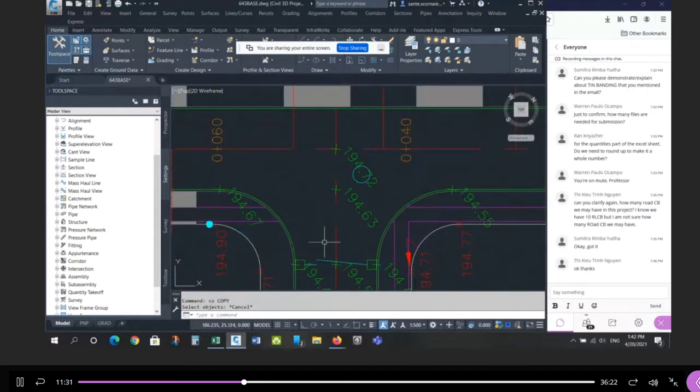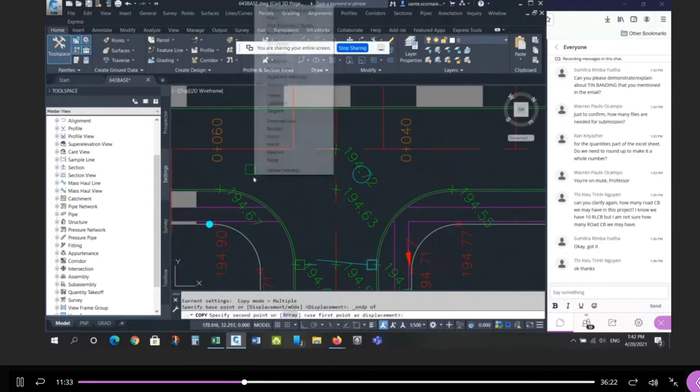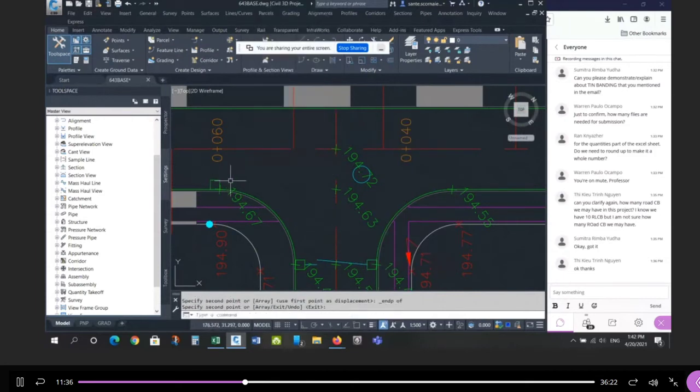So some municipalities say, you know what, you need a catch basin here to intercept some of the flow before it comes across where pedestrians are going to be crossing. So this is not because it's a low point. It's because it's before a sidewalk. Okay, I don't think they have that requirement in Milton, but that's something you might want to read about as well. Different municipalities have different standards.